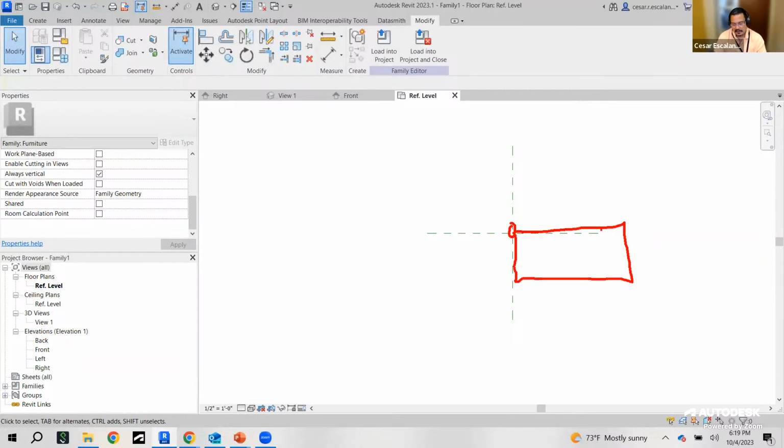So you click this point, then you click this point, you click this point, and then the user is just generating this row of wall cabinets. Or if you think it needs to be the center, then the insertion point could be at the back. I'm going to use the latter.